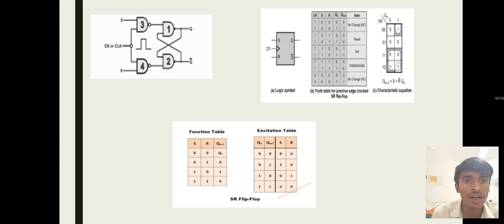The SR NAND latch forms the basis of many flip-flops, where the inputs determine the output by setting or resetting the stored bit, with feedback maintaining a stable output when inputs are inactive. Edge-triggered flip-flops use additional logic to respond precisely at the clock transition rather than being sensitive to input levels at all times.